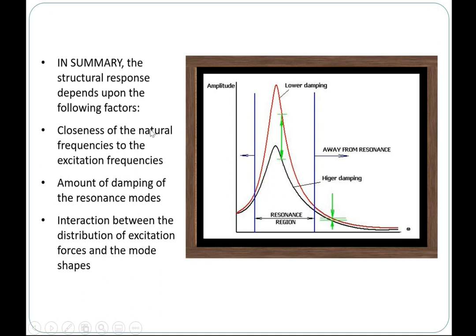With all this information, then I can explain, like what I have demonstrated to you, why the vibration is high: because it is close to a natural frequency. If you know where the natural frequencies are, then you know when resonance will happen.